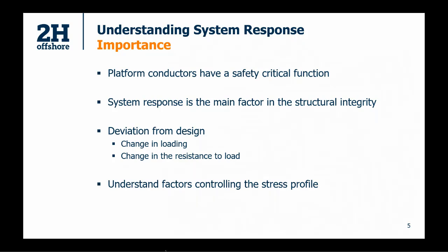So how the system responds to environmental loading dictates the magnitude of the bending loads, which then dictates things like the connector capacity and whether that connector utilization is acceptable. And also the response of the system dictates what the stress profile looks like, and the stress is what drives the fatigue. So it dictates both the location that you expect the fatigue to occur and also the severity of the fatigue damage.